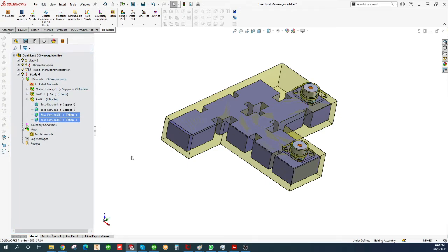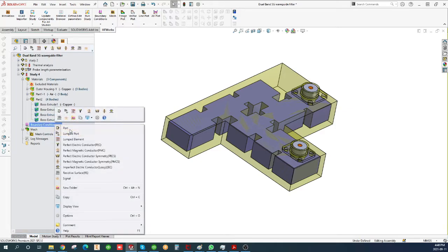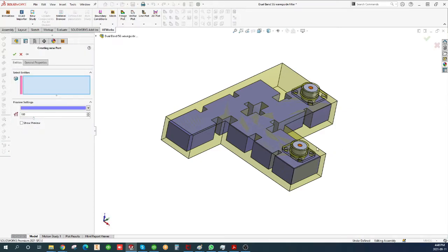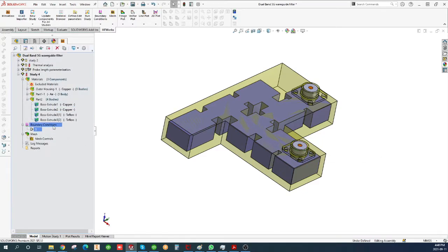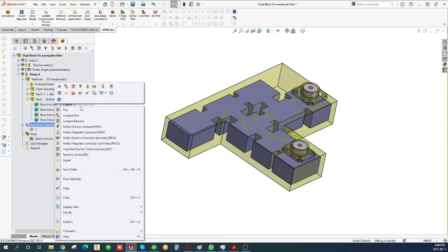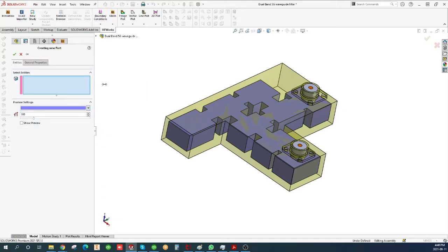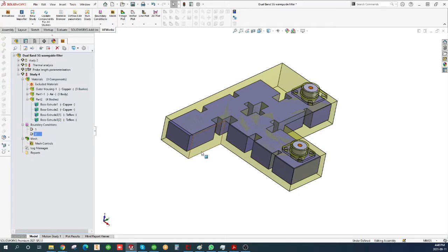So it's so simple. Boundary condition, actually there are only 2 boundary conditions to apply here. It's port 1, that's the coaxial cable, port 1, and port 2. Click. That's all you need to do. As far as meshing, you don't need to mesh because you selected adaptive meshing.